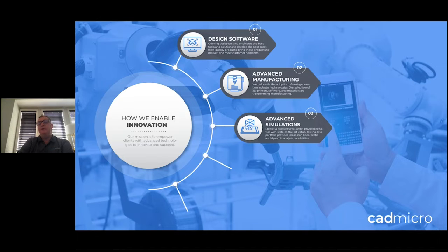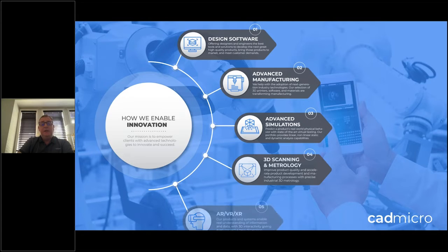I mean, Visual Components can be seen as a simulation tool because you're getting at where the bottlenecks are, what's the cycle time, statistically, what's the throughput going to be if I put in a Monte Carlo simulation or a normal distribution or chance into my simulation. You can do validation on simulations that you couldn't do with linear programming or couldn't do using a solver in Excel. We also get involved in 3D scanning and metrology. Again, Visual Components has a role to play because you can bring in factory layouts that you've scanned with a LiDAR scanner into the tool.